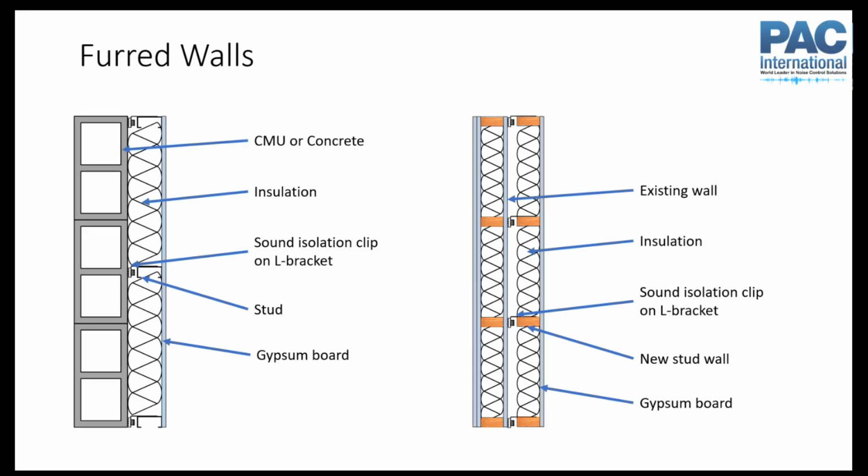On the right, similar sort of situation, like say you've got kind of a strip mall situation, right, where you've got a bunch of different tenants next to each other, and you've got a wall that already exists that's pre-built between two different tenant spaces. That's often a fire-rated wall, but usually not that great for acoustics. Typically, a new tenant moving into a space doesn't want to touch that existing wall. You want to build something outside of it.